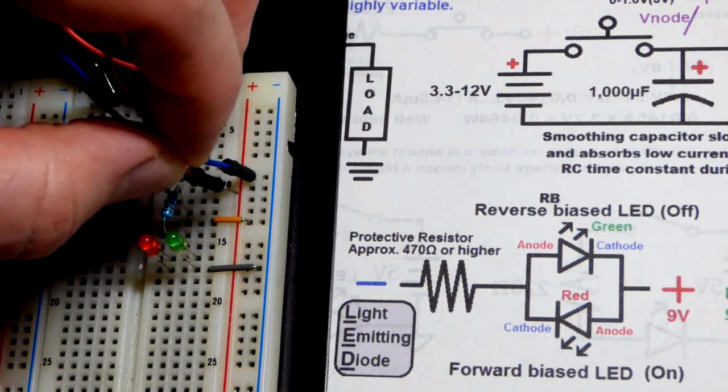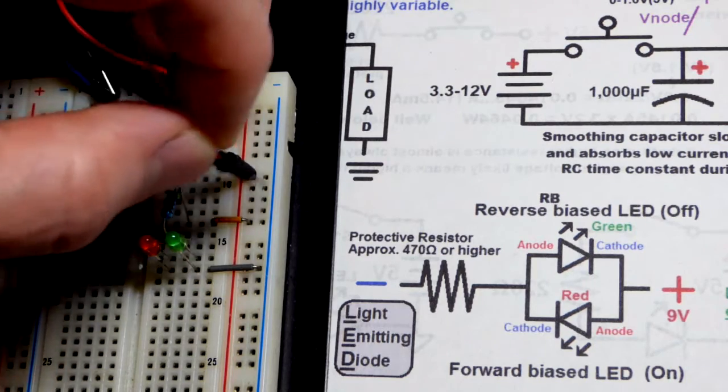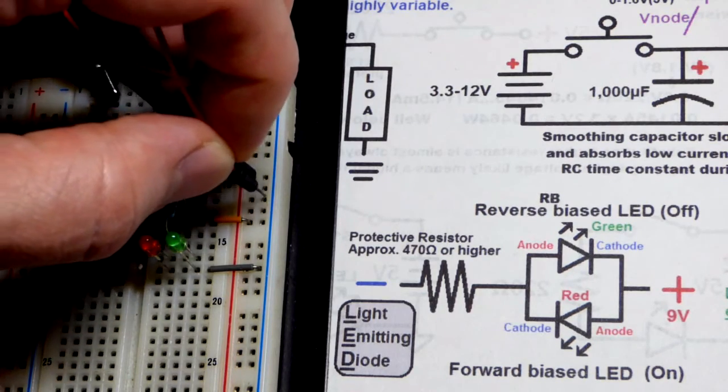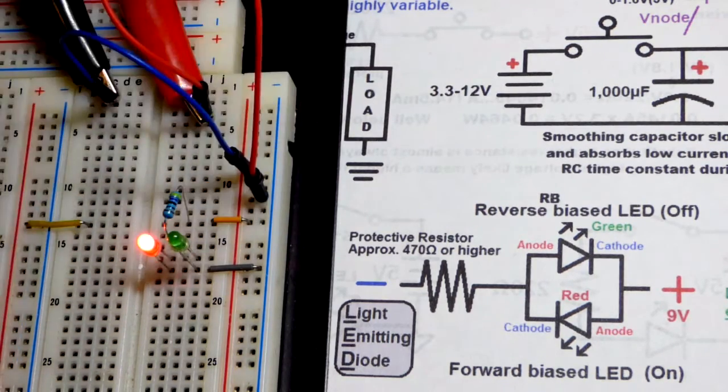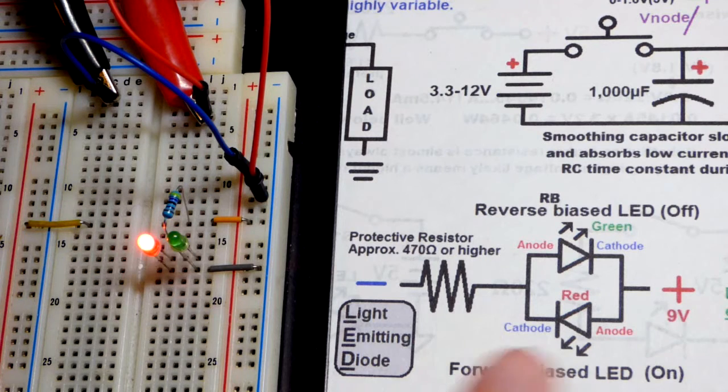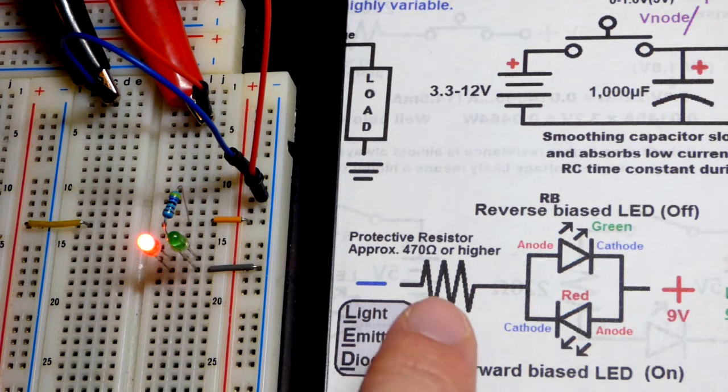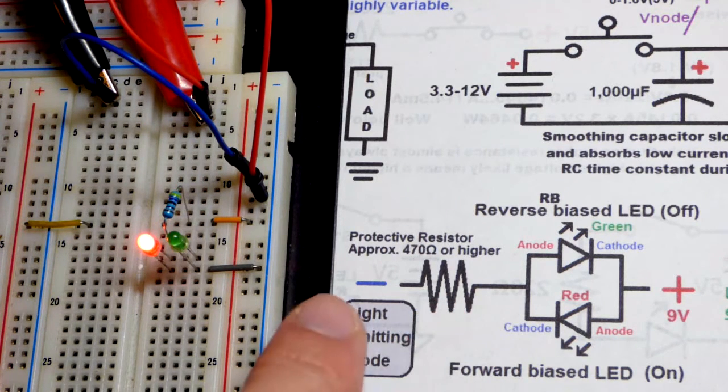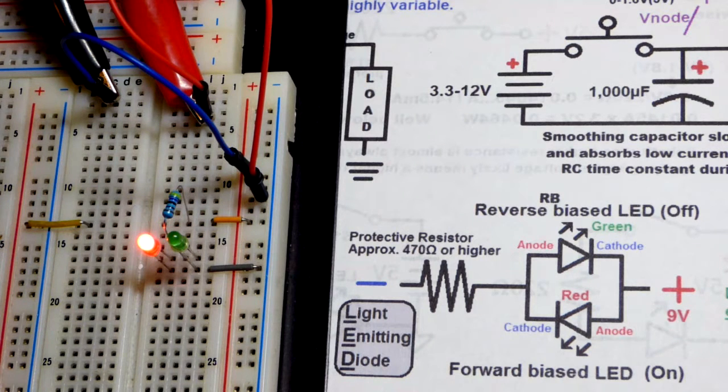So you're supposed to put positive to red, negative to blue, but you don't have to. The board doesn't care. There we go. We plugged it in. So now we have the red LED lit up. Red LED is forward biased. It has the same resistor protecting it, with the same power supply, it's not nearly as bright.